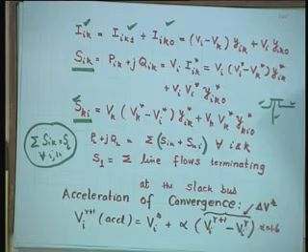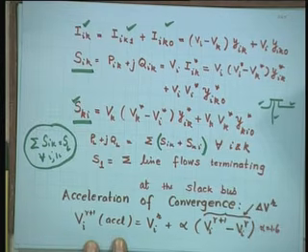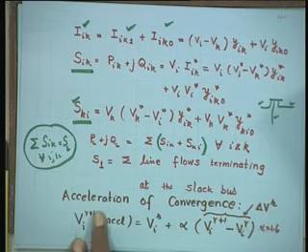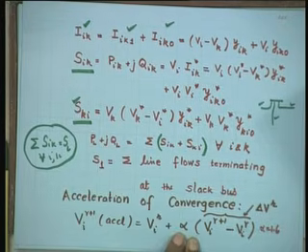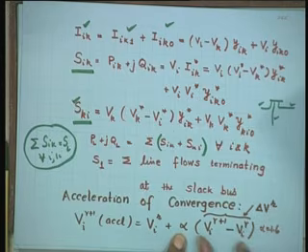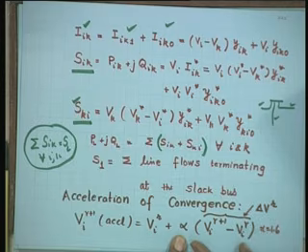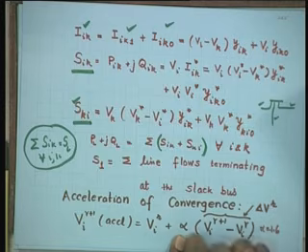So, in power system also there are some people who want to have fast convergence, they cannot wait, they have no patience. So, for acceleration of convergence, there is a formula: Vi (r+1)th accelerated value is Vi rth value plus alpha times the difference between the two iterative values of the voltages. Now, this alpha does the trick. Alpha is called acceleration factor.